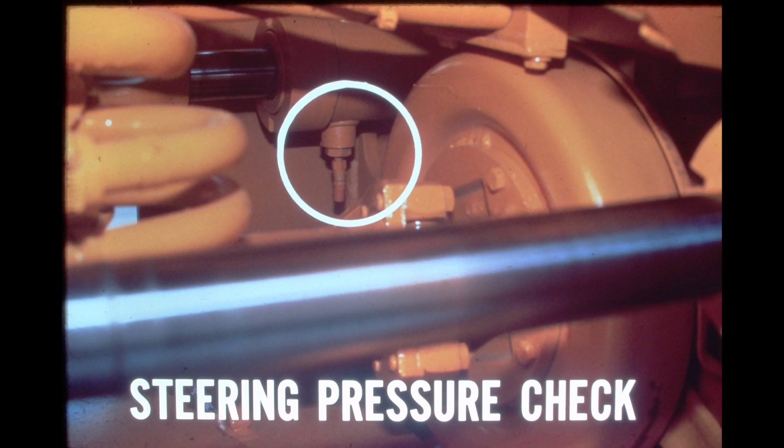If the pressure is incorrect at both high and low idle, adjust the steering system relief valve. The pressure should be 2,000 psi. If the pressure is as specified at high idle and not at low, the system relief is probably okay, and the problem would be internal leakage in the cylinders or both the steering and the switch pumps. Check these components for excessive heat. If the pressure is as specified at low idle and not at high idle, the steering pump would be at fault.